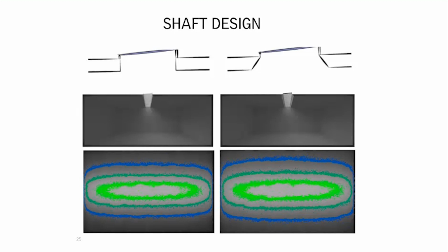Now, how does this factor in with energy? Well, if you could flare the light shaft and have better design at the ceiling level, you could actually reduce the size of the skylight a little bit and still get comparable amounts of daylight. So this type of approach is similar to what I was suggesting earlier with the daylight modeling and doing an iterative design with the energy modeling. You can do little things like this and you could reduce the size of the skylight, still get good daylighting, but reduce the energy loss in the wintertime through that skylight. So little tricks like this go a long way.